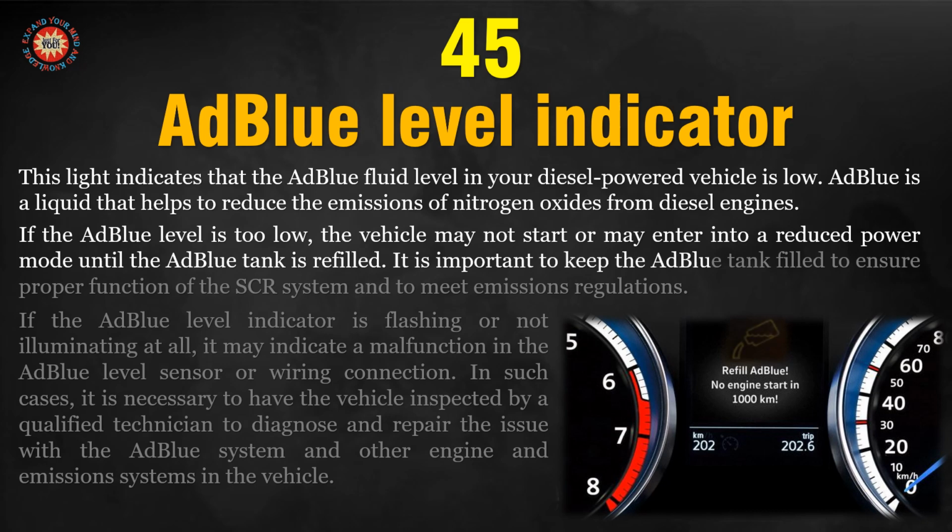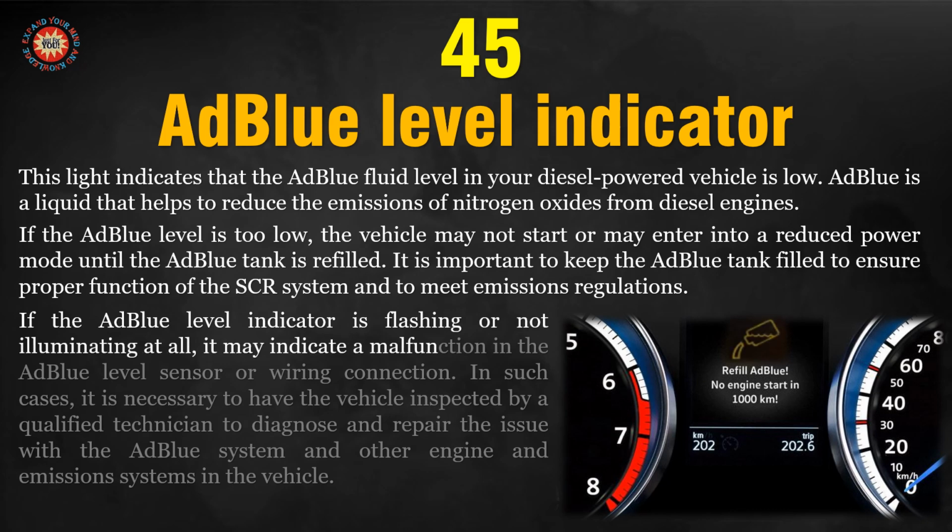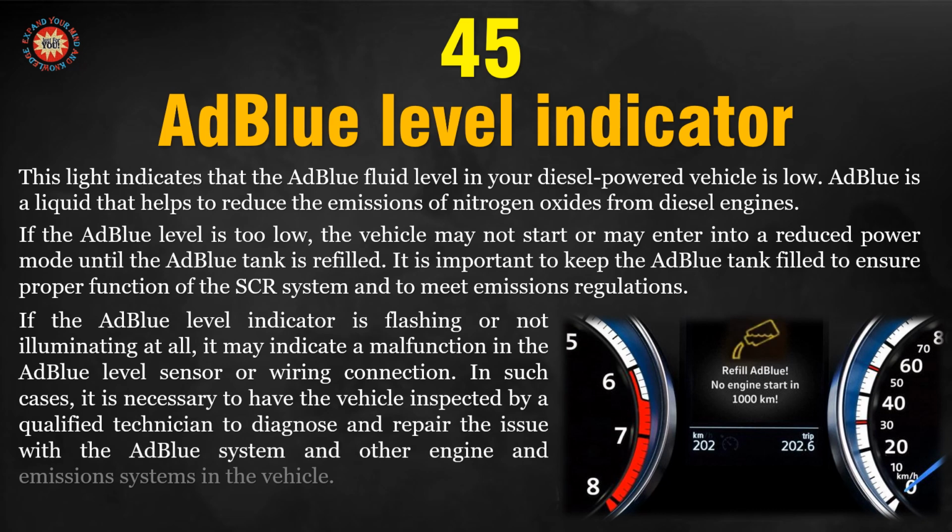It is important to keep the AdBlue tank filled to ensure proper function of the SCR system and to meet emissions regulations. If the AdBlue level indicator is flashing or not illuminating at all, it may indicate a malfunction in the AdBlue level sensor or wiring connection. In such cases, it is necessary to have the vehicle inspected by a qualified technician to diagnose and repair the issue with the AdBlue system and other engine and emissions systems in the vehicle.